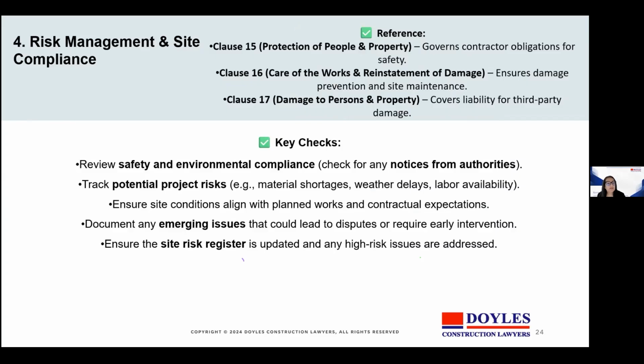Site records form the backbone of delay and disruption claims. If it's not documented at the time, it's really hard to prove later. And so it's important to review safety and environmental compliance, track potential project risk, document any emerging issues, and ensure a site risk register is updated progressively as the project advances.